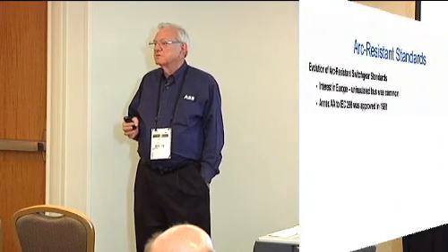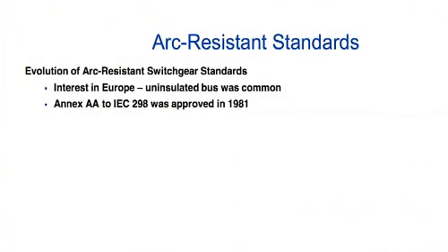And why Europe? Well, Europe, unfortunately, in the IEC design of switchgear, used buses, primarily the main bus, without bus supports between the frames. This has been universally true in Europe for many, many years. Well, they discovered that over this period of time, if you had a bus fault, it would tend to move right down the busway.